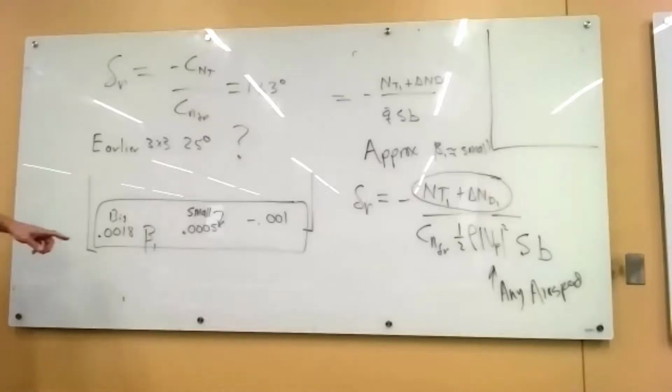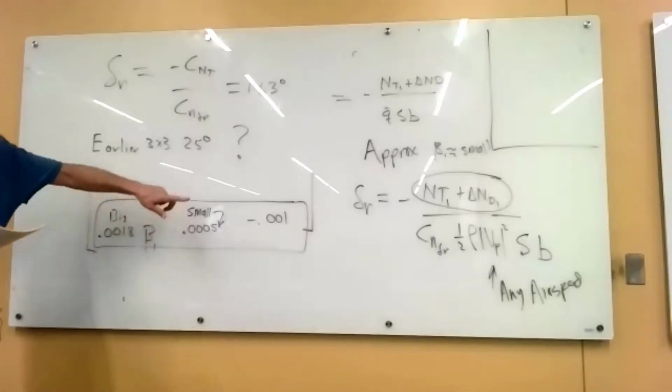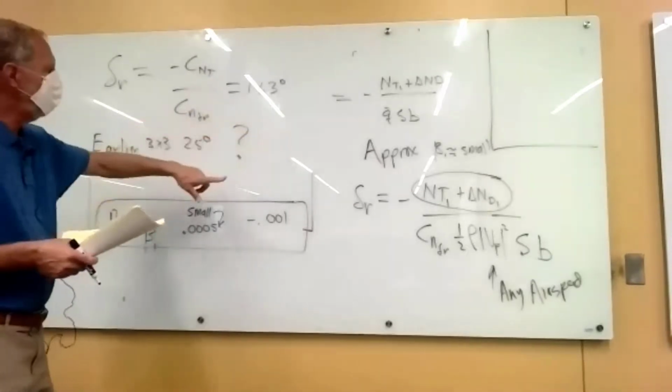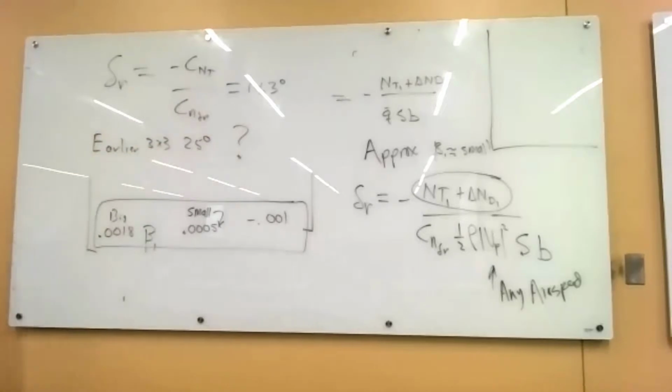And in fact, if you plug in the value of beta into the full equation, you don't neglect the beta, then you find out you get pretty close to the right rudder amount. But we don't know what beta is because we haven't solved the 3 by 3. So you say, well, why is this useful?